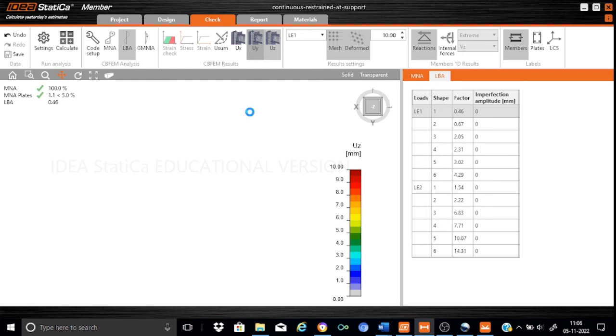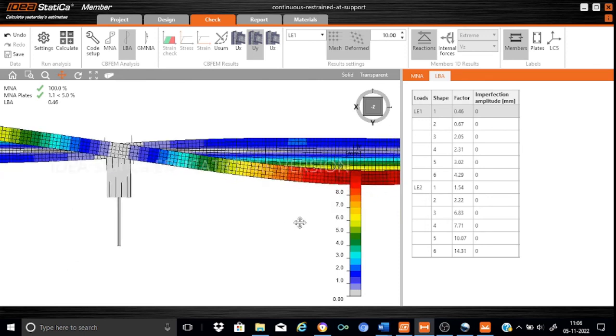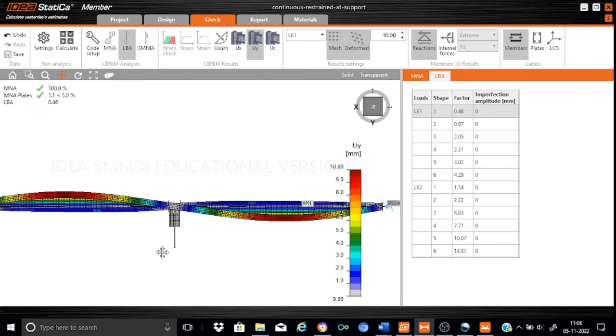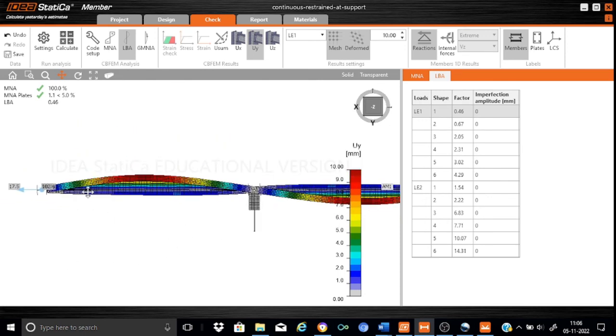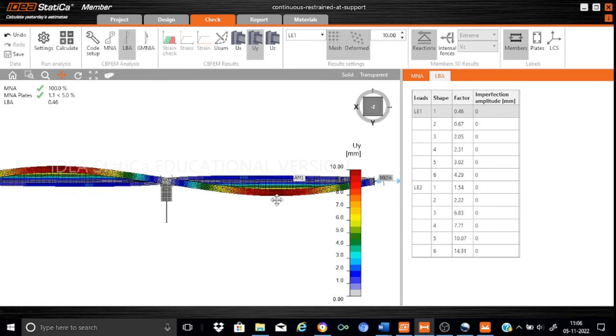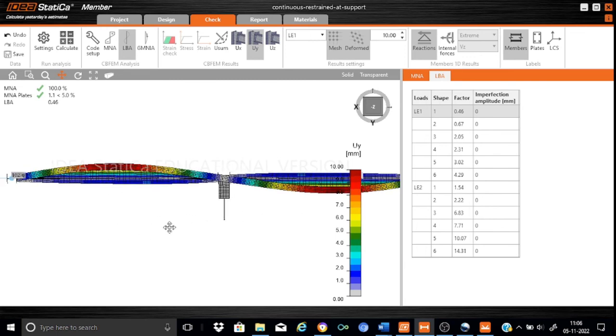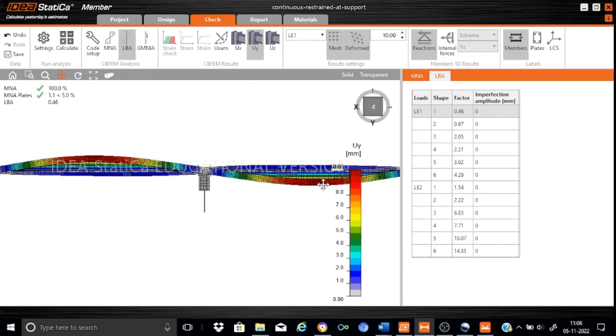So when it is a UI, it will provide you the total deformations in the buckling. So look here. You'll find that in this portion the out of plane buckling deflection is maximum, and here also the same. So this is what we call the fundamental mode of buckling here. From this we can very easily conclude one thing.